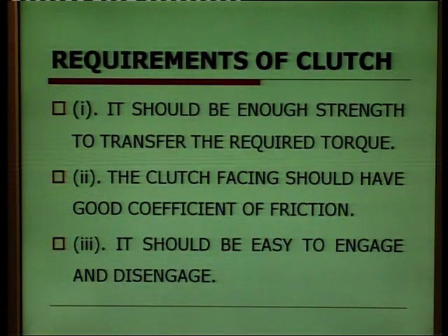Then what are the requirements of the clutch? Number one, it should have enough strength to transfer the required torque. Number two, the clutch facing should have a good coefficient of friction. Number three, it should be easy to engage and disengage.